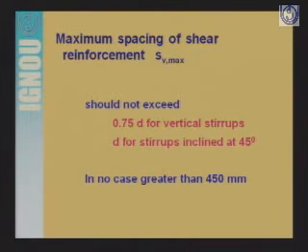So 0.75 d should be the maximum spacing, meaning this limit should not be crossed. It should be less than or equal to 0.75 d for vertical stirrups.